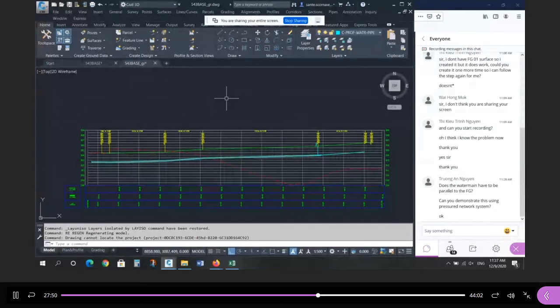You can put in the flow in each pipe. And again, in my experience, sanitary and storm flow using AutoCAD to design the size and the slope you need is more trouble than it's worth. So we typically use an Excel spreadsheet, and that's how I'm going to teach it next semester as well. I know you used one in MPT. We're going to use one as well.